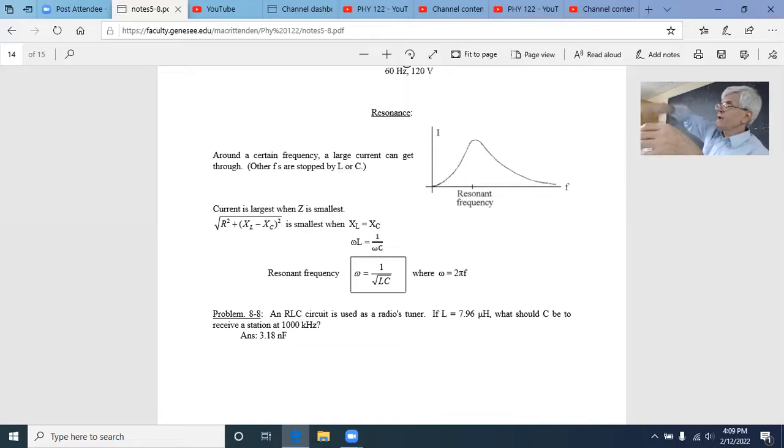Okay, the swing goes back and forth real good after you've pushed it a number of times. If you were to be foolish enough to try and push the swing at some other frequency, it wouldn't work very well at all. So just like pushing on a pendulum, the pendulum resonates if you drive it at its natural frequency. It's the same with this RLC circuit.